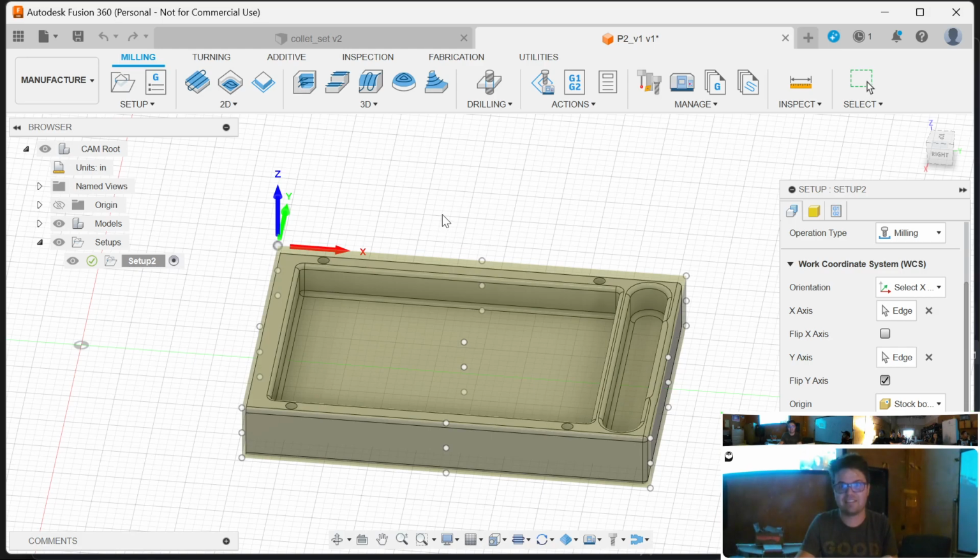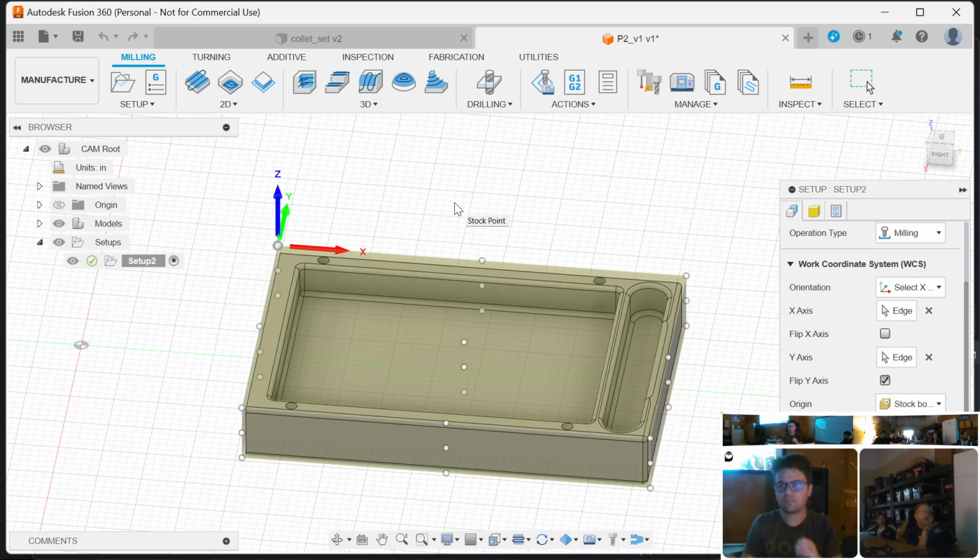Does that all make sense? Question, so like on a 3D printer, you've got limit switches, so it automatically does something. Does the Tormach have limit switches where it automatically checks where your 0,0 is at? Yes, so both the Tormach and the ShopBot have limit switches on them and go through a homing routine and set the machine's G53, the machine's 0, from its limit switches. Okay. Cool.